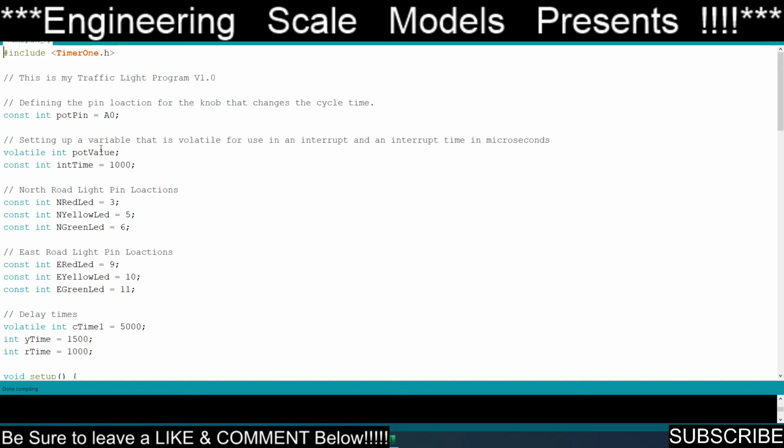Now, for the programs that are running in the interrupt, you need to make the integers, the variables it's changing, volatile. So the Arduino knows at any time this integer can change without notice in the loop program.